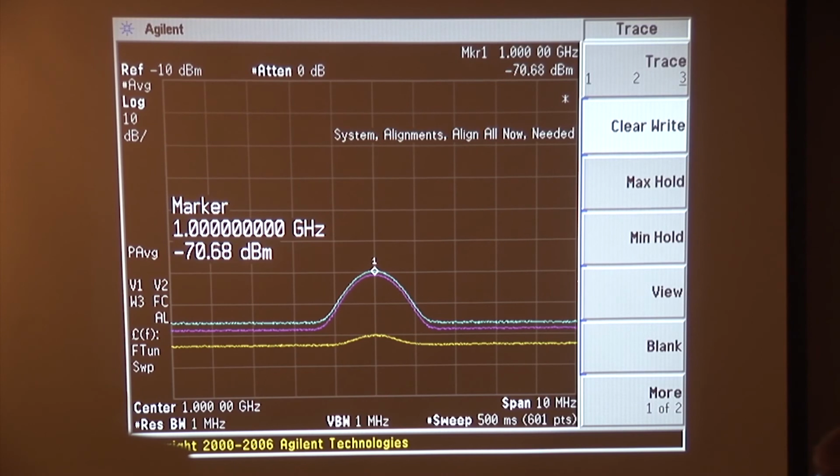But you don't really need to put in that last 4 dB of attenuation. And then Steve, I'm going to take you up on your suggestion. I'm going to take the attenuators out of here, go back up to the first state, and we'll do it a dB at a time with the spectrum analyzer's built-in attenuation, which is oh so handy to have, because this spectrum analyzer allows you to vary attenuation a dB at a time, which older analyzers don't. Older analyzers force you to snap in 10 dB at a time. You could do that here, but then you'd have to choose between 10 dB versus 20 dB. But we don't have to do that. Here we can go a dB at a time.